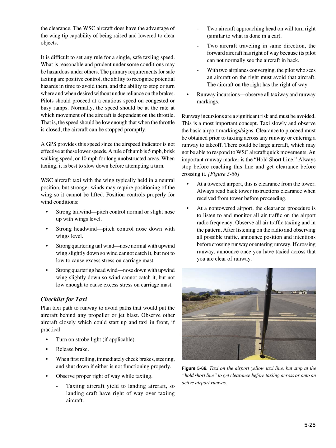Runway incursions: observe all taxiway and runway markings. Runway incursions are a significant risk and must be avoided. This is a most important concept. Taxi slowly and observe the basic airport markings and signs. Clearance to proceed must be obtained prior to taxiing across any runway or entering a runway to take off. There could be large aircraft, which may not be able to respond to WSC aircraft quick movements.